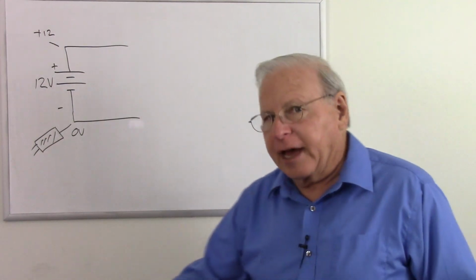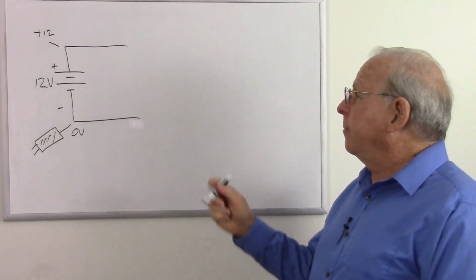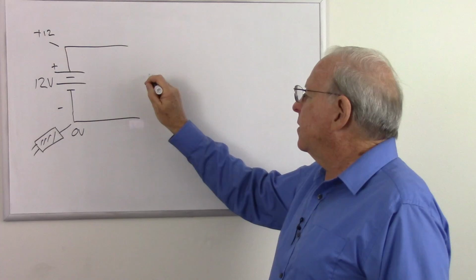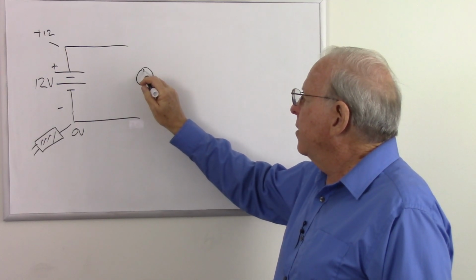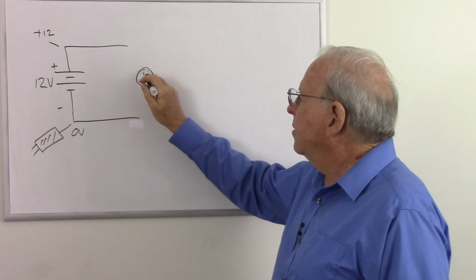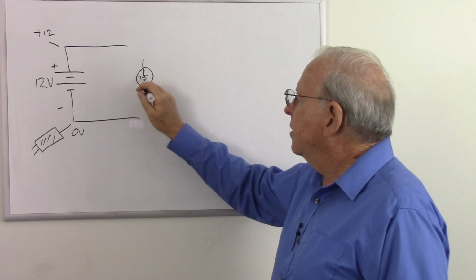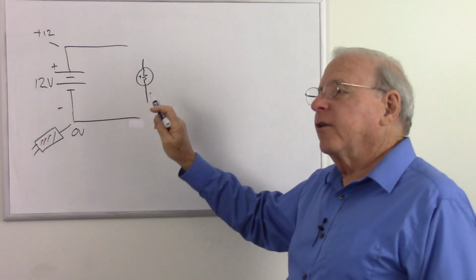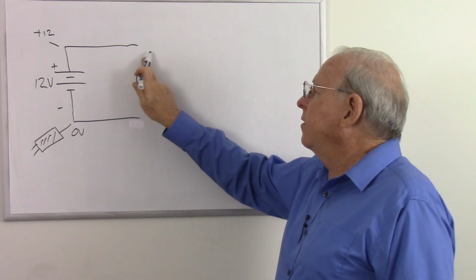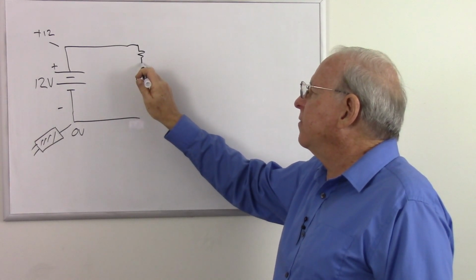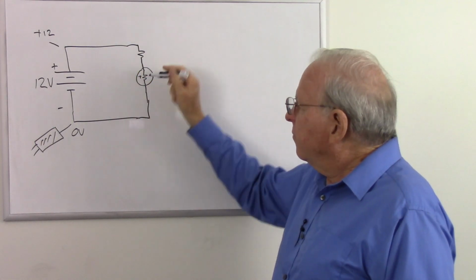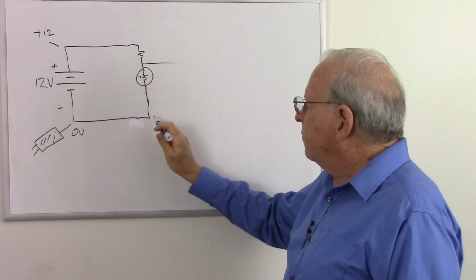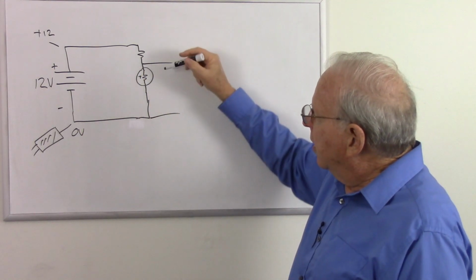Let's say I have, how about a temperature sensor? Let's put that as a thermistor here. And let's say that for that particular thermistor, let's put some bias on there. So we need some kind of a voltage to get it working, and we can pick off a voltage there. So there's our ground, there's our pick-off voltage.